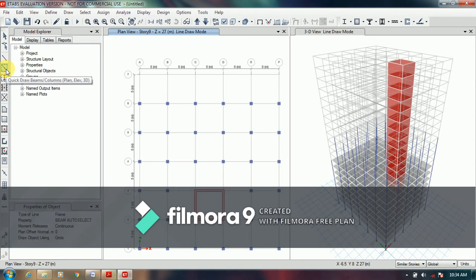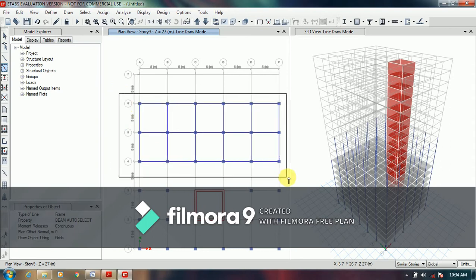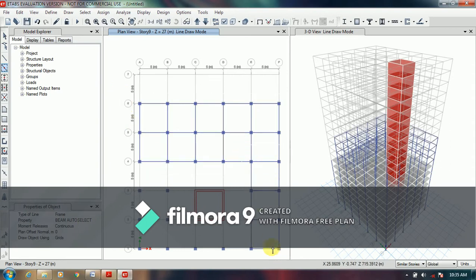So just go to quick draw beam option. Here we are having the property as beam auto select, so now we can draw the beam. Now draw the beam near the shear wall one by one. Now we have drawn all the beams and columns, so now it's time to draw the slab.